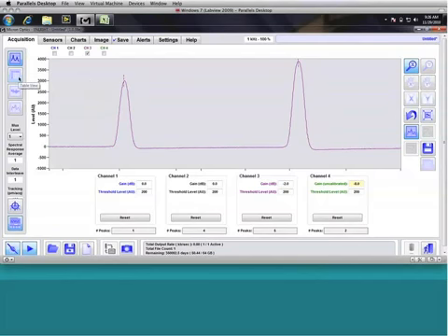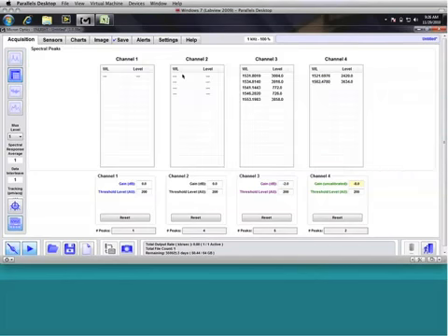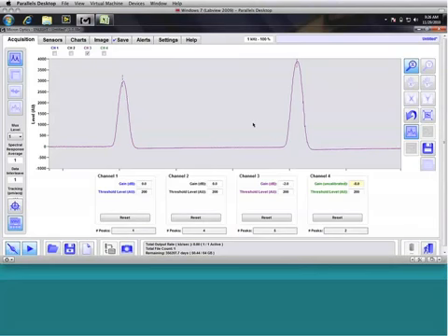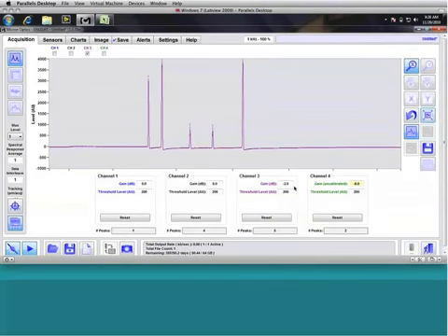I'm going to move over to the table view quickly and look at channel 3. Now we have these sensors at 1531, 1534, 1541, 1546, and 1553. So let's go back to the graph and demonstrate why that spectral tracking is important. We can do that either through an attenuation of the fiber, changing of the gain, or I'm just going to change the detection threshold for channel 3 and increase that.